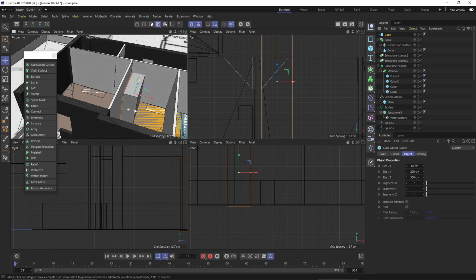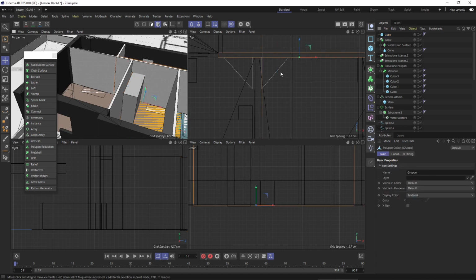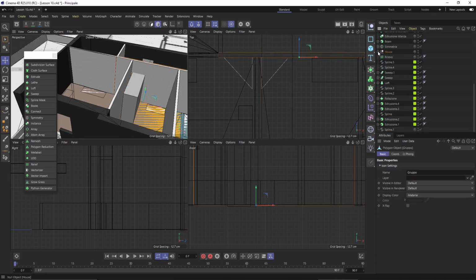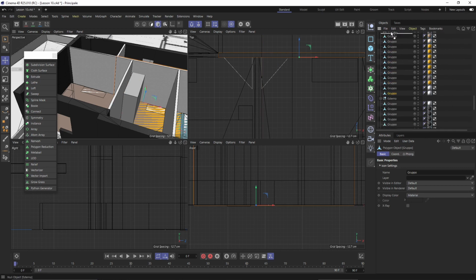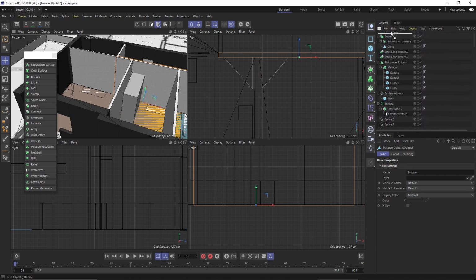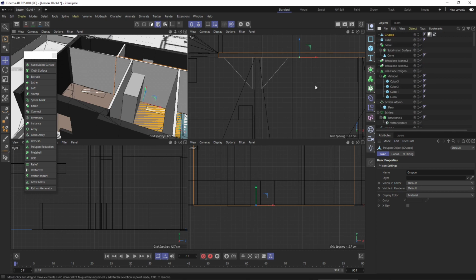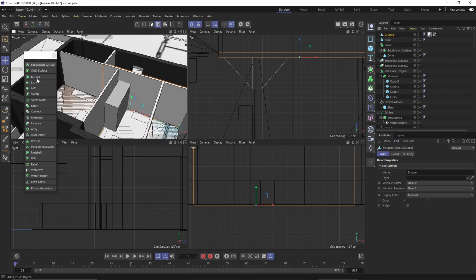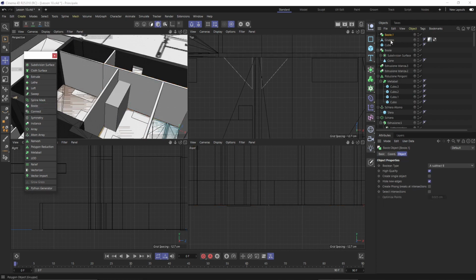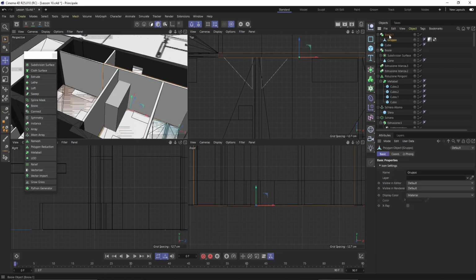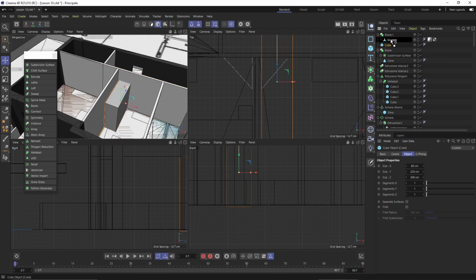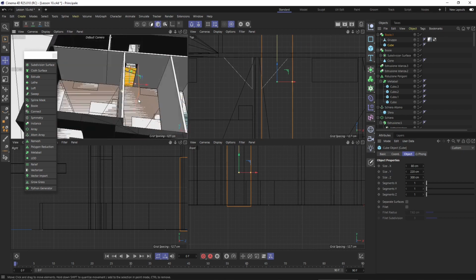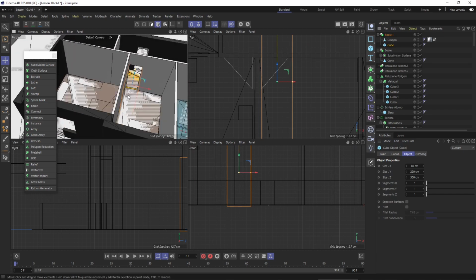What you can do here is select the first one, which is going to be some extrusion somewhere. I need to find it. There it is. So I want to take this outside, all the way up. Now I want to create a Boolean, and I want to subtract the cube from this one. So I'm going to click and drag and place it just below the first group there. And you can see I am creating a hole. Now I can copy this and